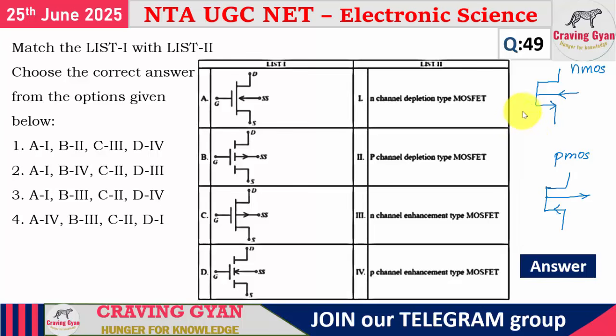In the case of enhancement, you have to create a channel. In the case of depletion, the channel will already be there. See, the channel is already drawn, so it is a depletion. Here it is enhancement. Here it is a depletion mode. Here it is enhancement. Now look at the things. You have to tell whether it is an NMOS or PMOS. The current is outward, but the substrate current is into. So it is NMOS depletion.